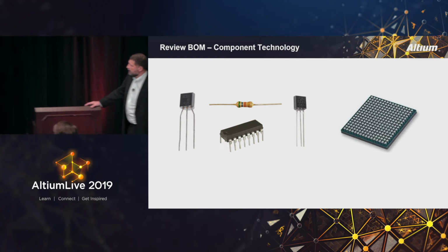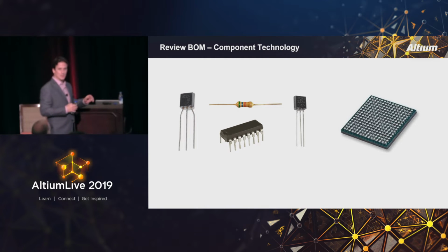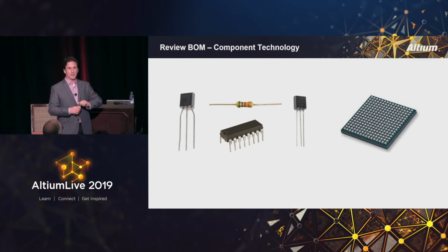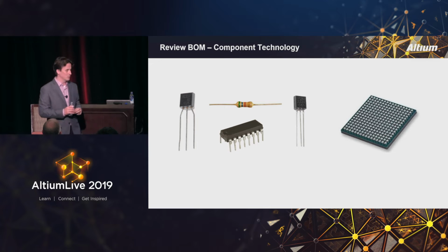I think another thing, at the other end of the spectrum, is through-hole parts. Every additional operation in assembly is going to cost you money, and through-hole parts might seem pretty benign in terms of technology, but they can be a huge cost adder to your assembly process.